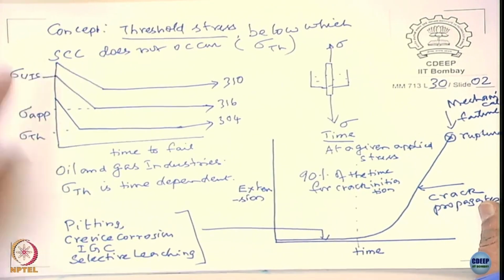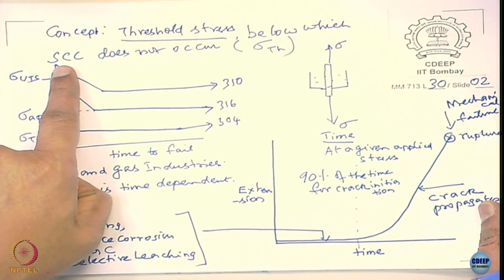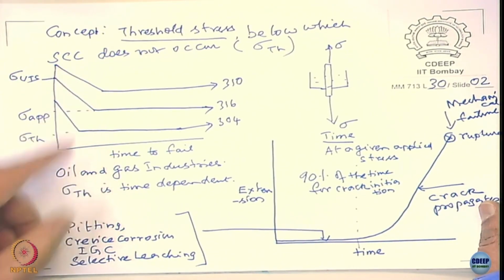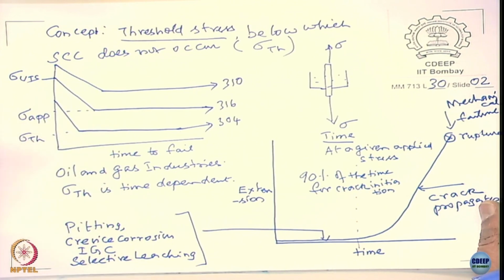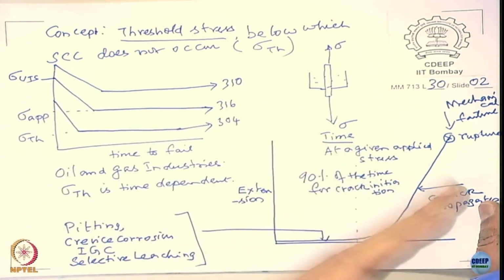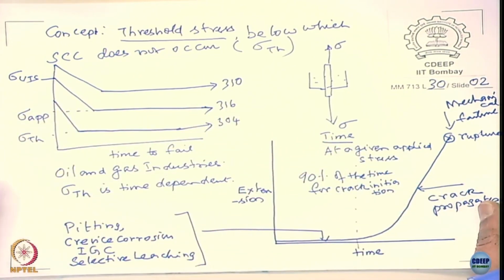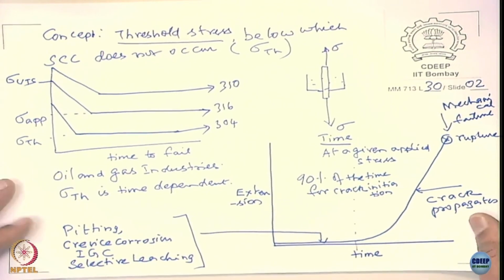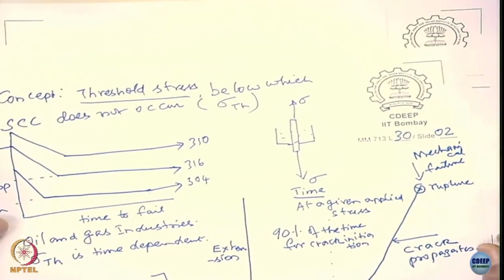You know, so you look at this here, right? What is this actually? This one leads to ultimate tensile strength, right? Yes, if you lower the cross section and keep the same applied load, the stress increases and ultimately that particular segment leads to a mechanical failure. Okay, that can happen in practice and it indeed happens in most cases actually.